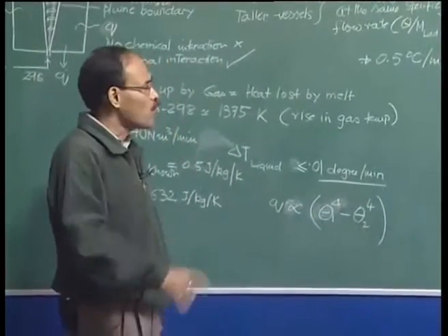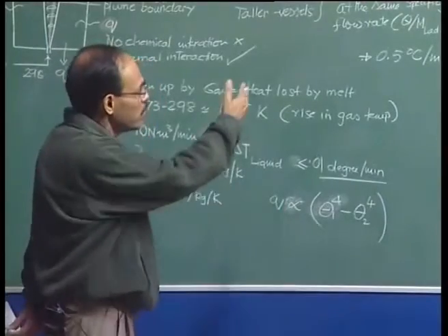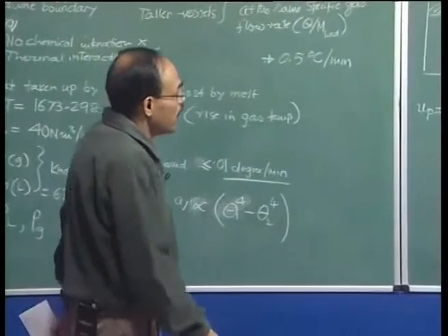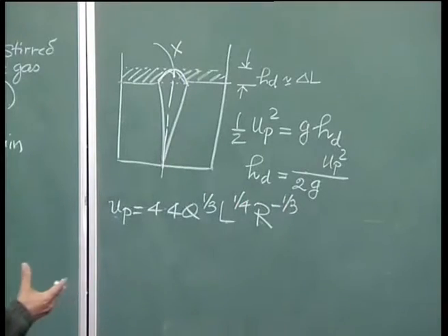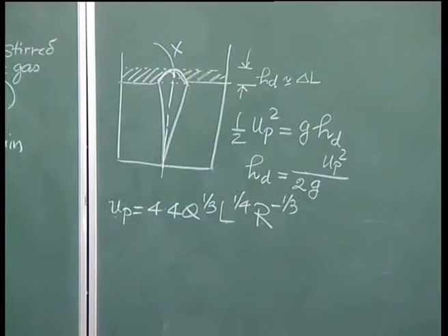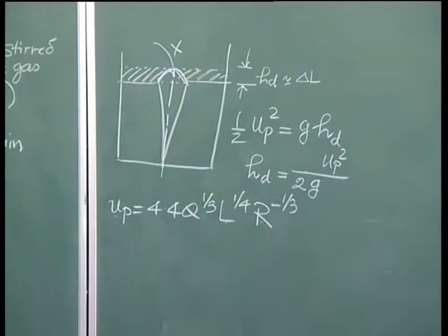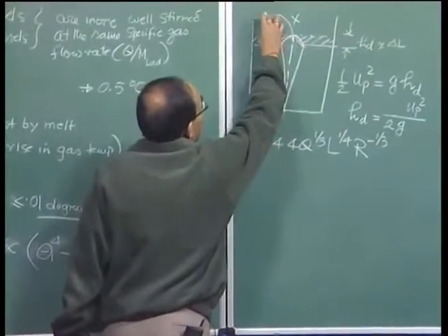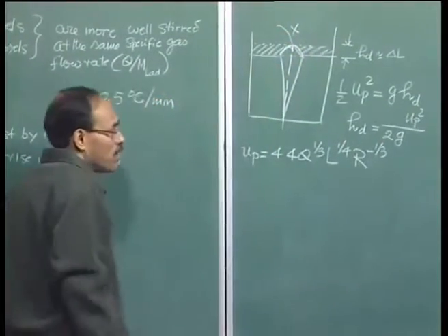I am going to talk about mixing, which is very important in the context of ladle metallurgy, within the next few minutes. So, during the final stage of ladle metallurgy operations, when we are injecting the gas at a very slow rate, 0.1 normal meter cube per minute per ton, we would really like to see that there is not much interaction with the atmospheric oxygen.